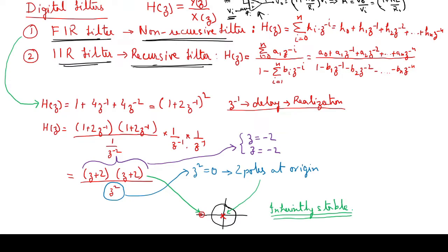This is the basic characteristic of an op amp. If there is a ground, then the other one also becomes a ground. But over here we are having Vi, because no current is flowing through. If no current is flowing through, the whole drop will be across over here also. So at the input, this non-inverting terminal will have Vi, and over here also we have Vi.